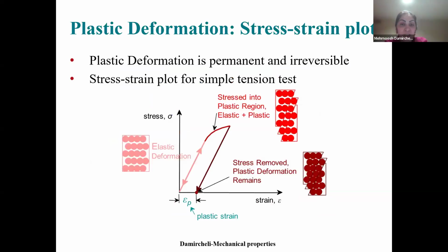Plastic deformation stress-strain plot. When we apply force here, we are in the elastic region. After the yield point, we enter the plastic region, meaning the curve is no longer linear, and the relation between stress and strain is completely non-linear.